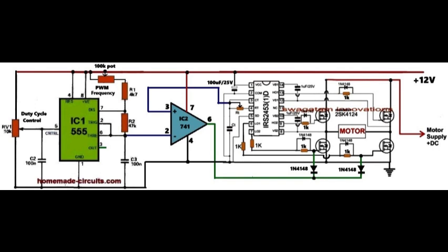The IC741 op-amp comparator. The slow triangle wave, which works like the reference wave, is derived from the RT CT junction of the IRS2453 IC. This ensures synchronization between the SPWM and the inverter's output frequency. The slow triangle wave is fed to the inverting input of the comparator.